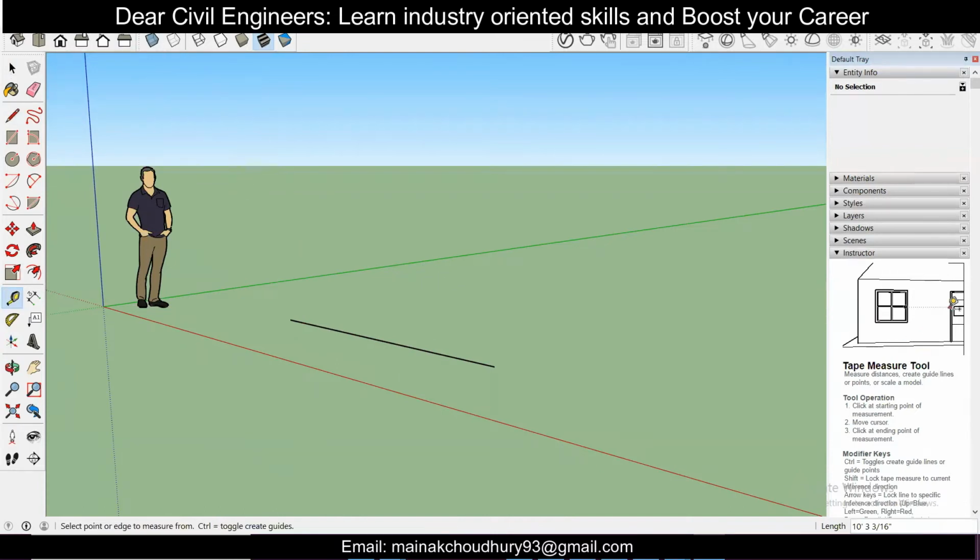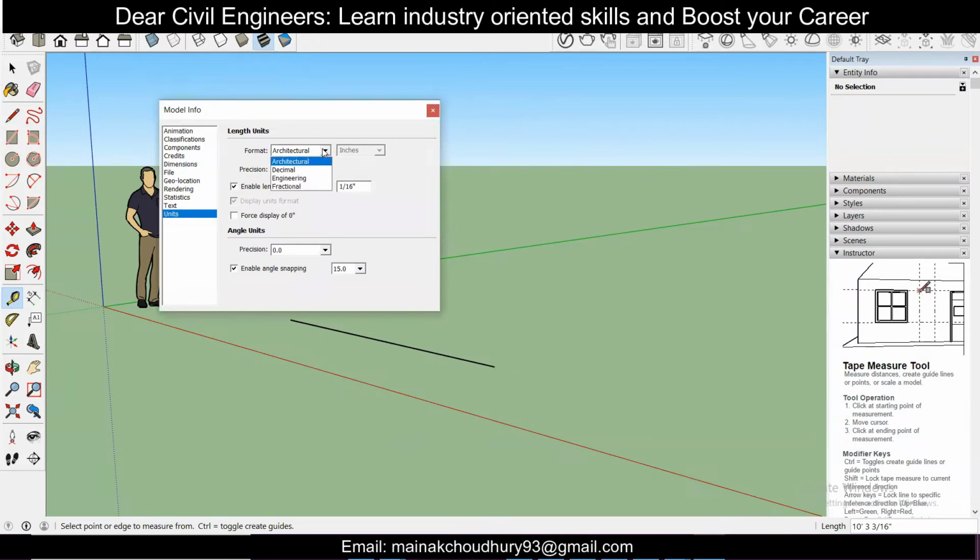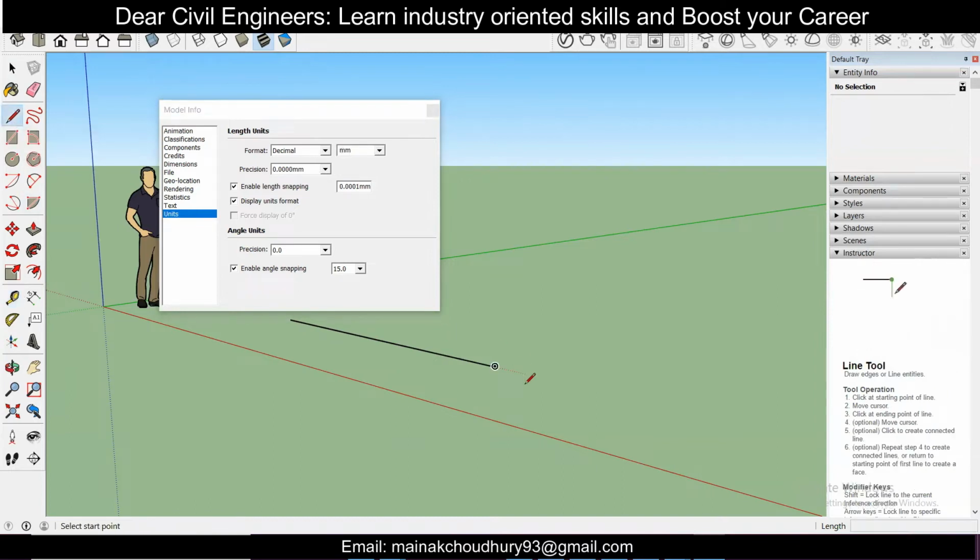Similarly, if you want different units, suppose you want to do it in mm, go to Window and go to your Model Info, make this decimal, then make this mm, and set the precision to 0 mm. Then just close it, or you don't need to close it as well. Just take this line and you can measure it here.